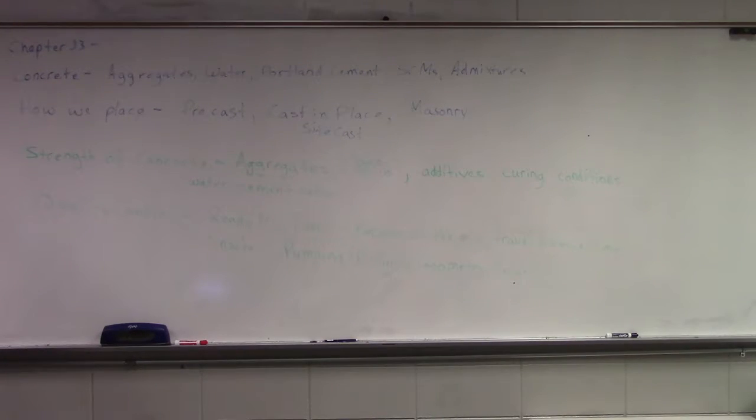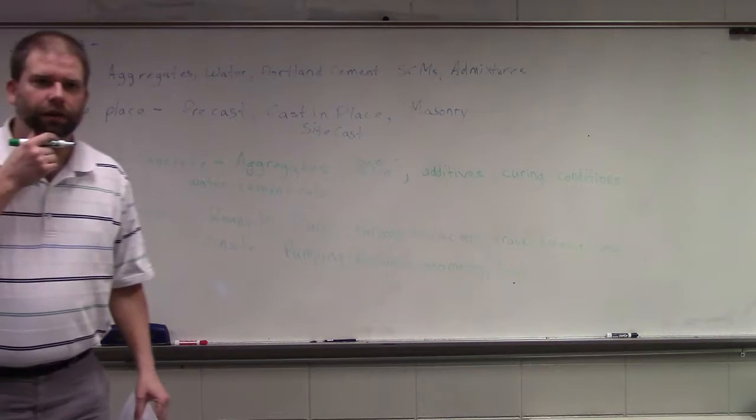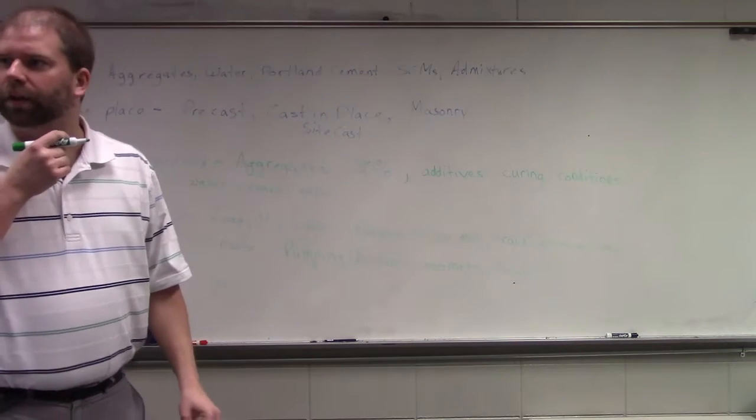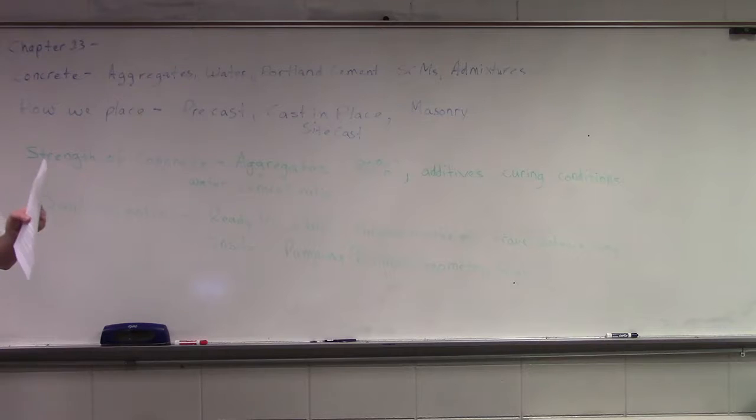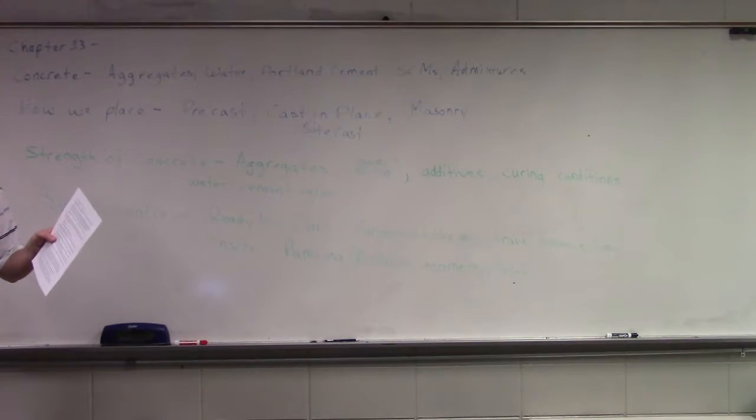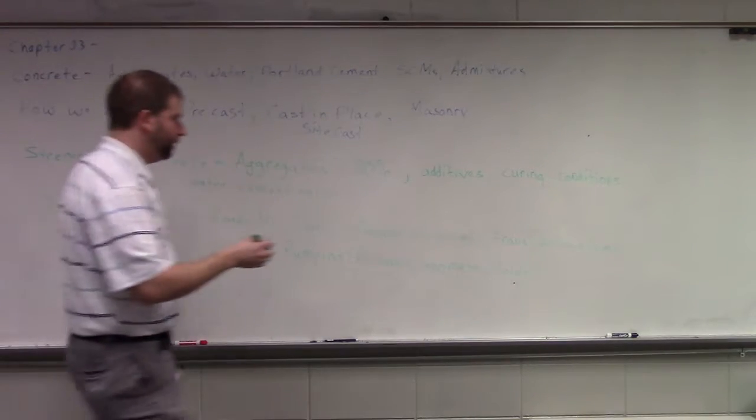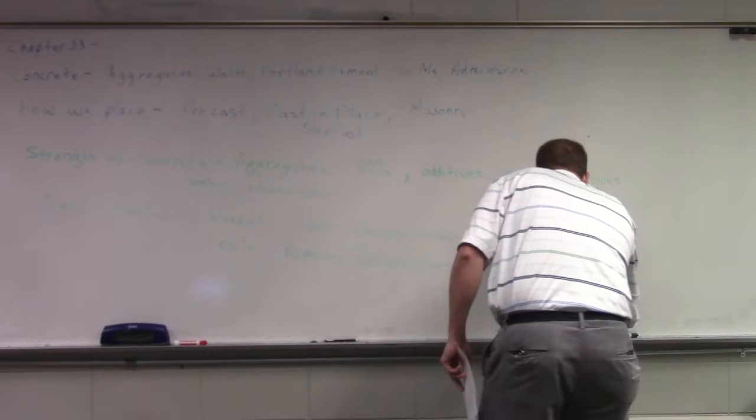What are other things that we need to do? It's something that we always have to do with concrete. Well, I shouldn't say always. We don't have to do it with self-consolidating concrete, but with conventional concrete, what do we always have to do once we get it into the forms? Spread it, finish it, level it? Yeah. Scrape it, level it, some sort of consolidation and finishing, right? Okay, so we have to be aware of our consolidation.